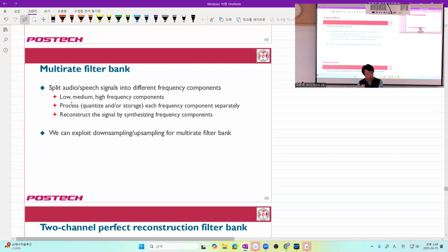You put a very small-size MATLAB-like general purpose computing software and let that do all the computing without implementing with hardware, but you implement these algorithms in software, which is much easier. You don't even need to consider this multi-rate conversion with upsampler and downsampler. Just insert zeros and filters, something like that, as you do in your homework.